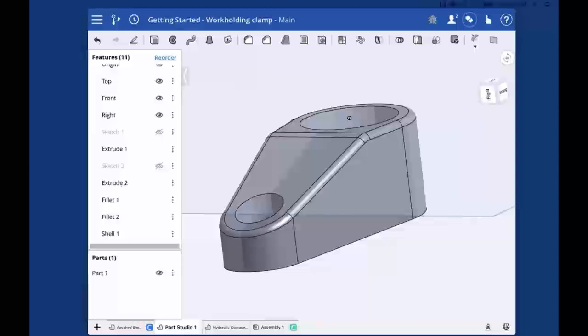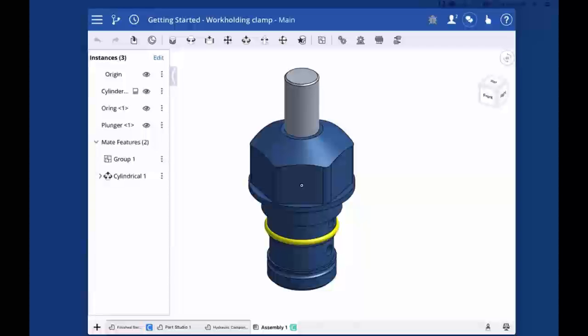So some things I want to point out. Up to this point, it's largely been sketch tools and feature creation tools. You create your sketch, constrain it, dimension it, and so on, and then you create a basic feature out of it. When we talk about assemblies, what we're really talking about is motion. I want to be able to test the motion of my assembly, and that's really where we get into mates and all the various things that get involved with assemblies.